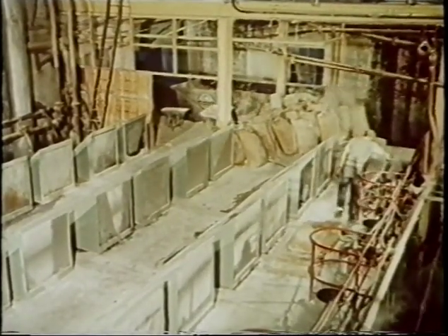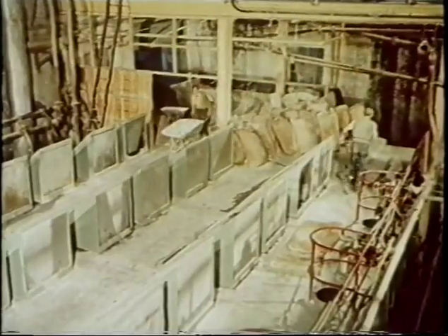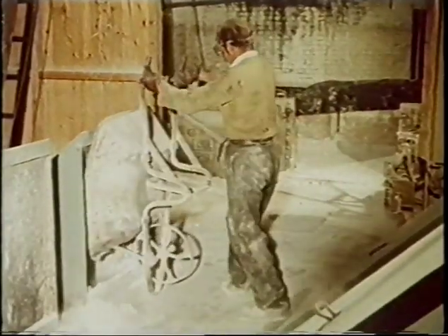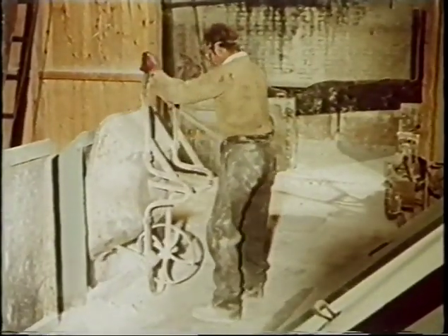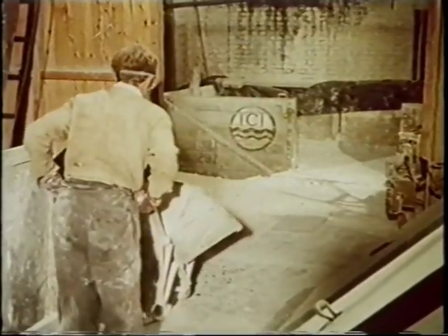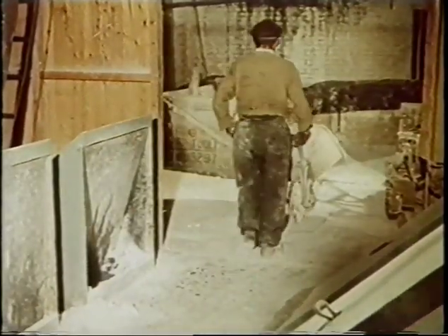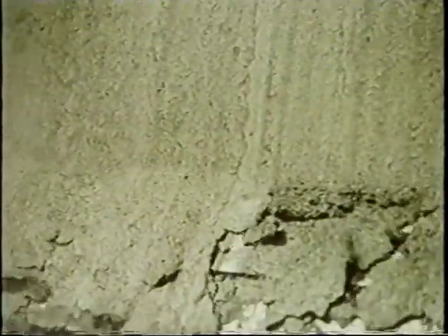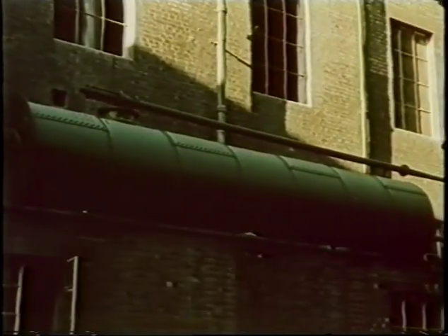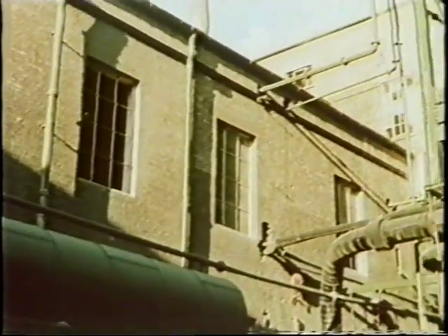To this mixture of fresh and recovered sodium carbonate, quicklime is added. Quicklime and sodium carbonate, when mixed together, produce calcium carbonate and caustic soda, the lime soda process. After causticizing, the caustic liquor is filtered out of the chalk sludge. It is stored until it's needed again in the digesters.